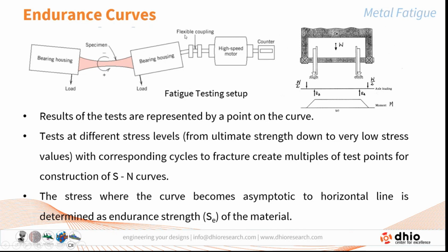And this is being connected with a flexible coupling, which in turn is connected to the high-speed motor, which can be used for conducting the experiment. Along with that, you have the counter, which gives us the number of rotations the motor is going to be running. Now, the setup is done in such a way that the circuit is linked to the counter. As soon as the specimen breaks, the motor stops, and thereby the number of cycles it has taken is also counted.